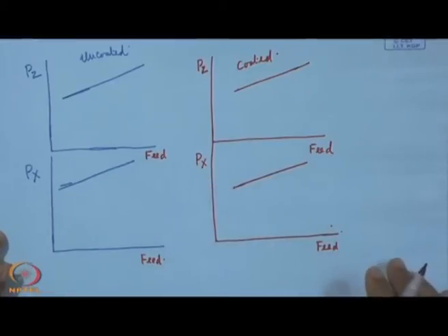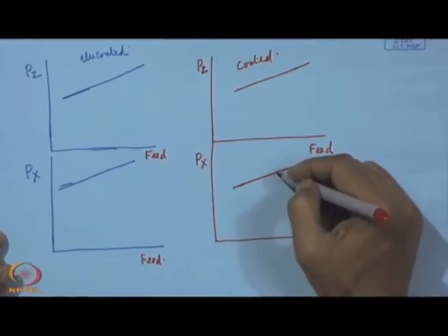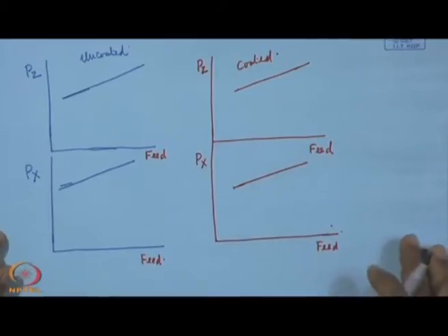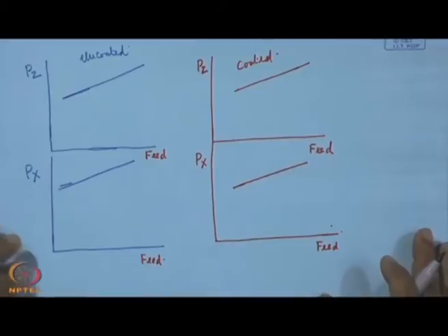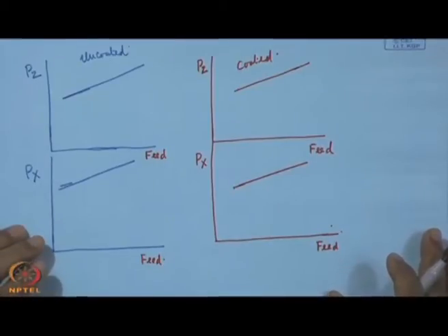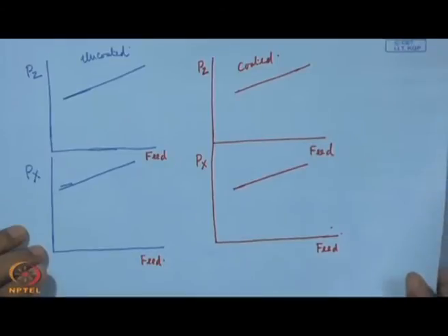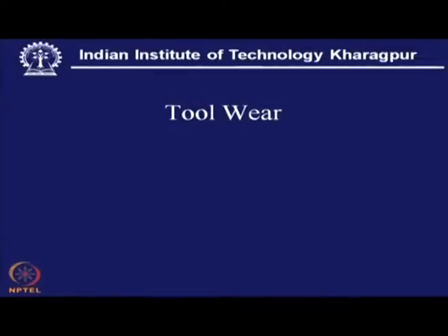So, this is most important: whether the line has been brought down quite substantially, and that will simply recognize the capability of titanium nitride coating, in particular in the low speed operation range. Now, when it comes to the high speed operation range, it becomes the wear on the tool. That means, in simple terms, this titanium nitride has two roles to play.